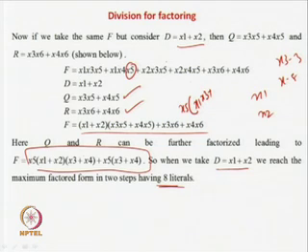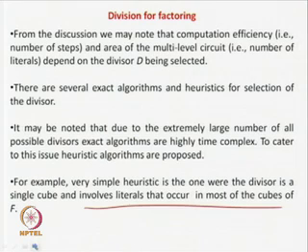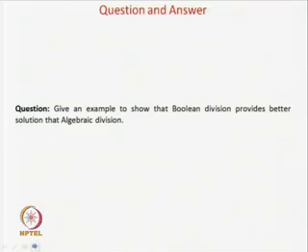So that is, if I take the literal which is common in most of the cubes, then I will be able to reduce, factorize the expression f in a much better way. So this is one very simple heuristic you can think of, but exact algorithms and better heuristics are more complex, okay. So with this we are closing this discussion, and we are coming to the question answer session.